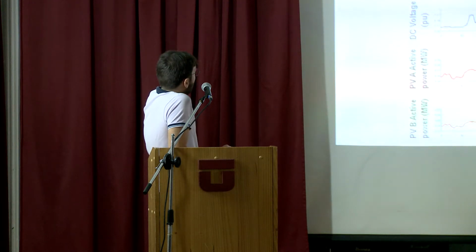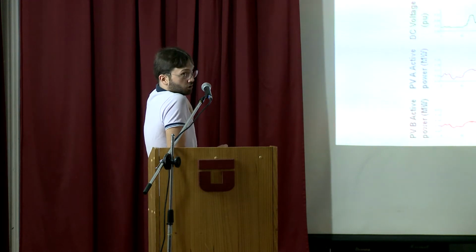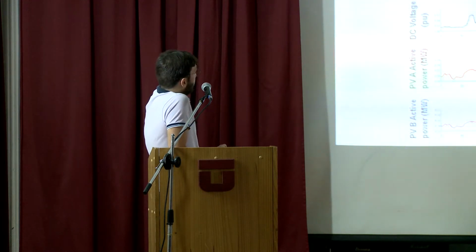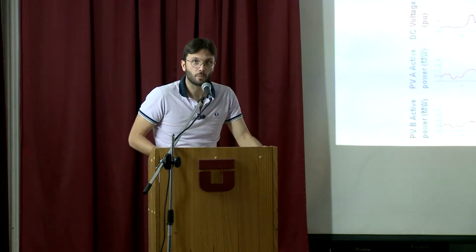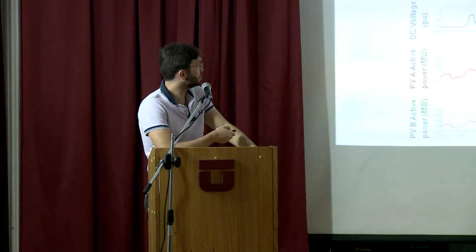This is 50.5, so the limit was 51.5, so this is actually control, it's not saturation. The controller finds the right frequency to keep the DC bus at a specific point, and we are controlling the power. So it works. With 10 Hz of PLL, it works.